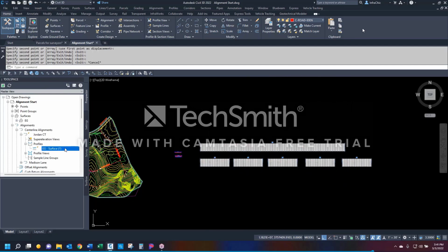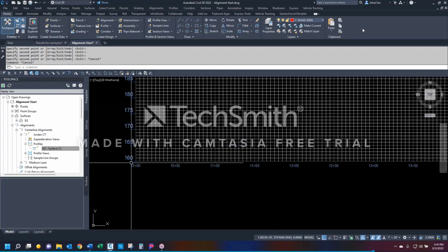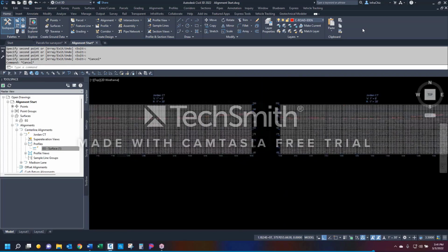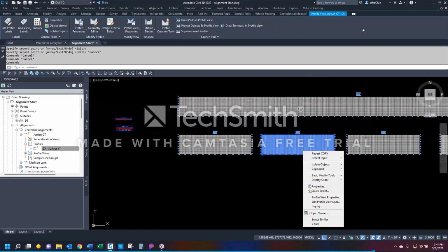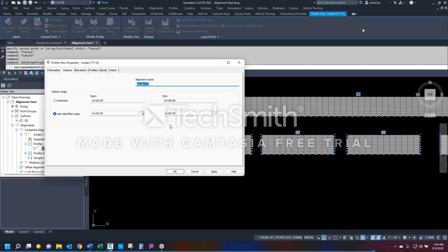4 different copies. Do you see any more copies of the profile there on the left over on Tool Space? Still the same one. Now, how do I fix this? Every one of these are identical. They all are 1,000, 1,000, and 1,000. Okay. Select the profile view grid, right click, go into profile view properties.